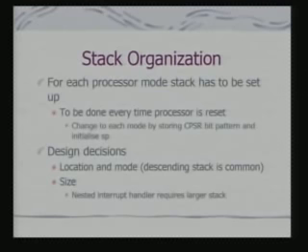I shall have a stack in the memory. A stack is a memory area, and that memory area will be different for different modes. The stack that I am using in user mode is definitely not the same as the stack area which I might be using in FIQ mode. So, I have to appropriately set the stack pointer values, and that is typically done during the reset mode.